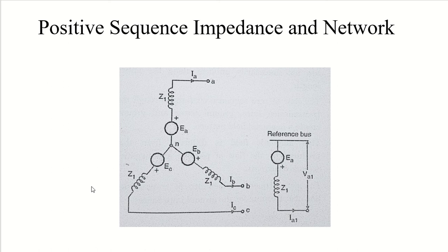And the flow of this only positive sequence current which has been generated will produce the armature reaction in field, and because of that it will rotate at synchronous speed in the same direction as the rotor is rotating. So with respect to field, the excitation will remain stationary, right?